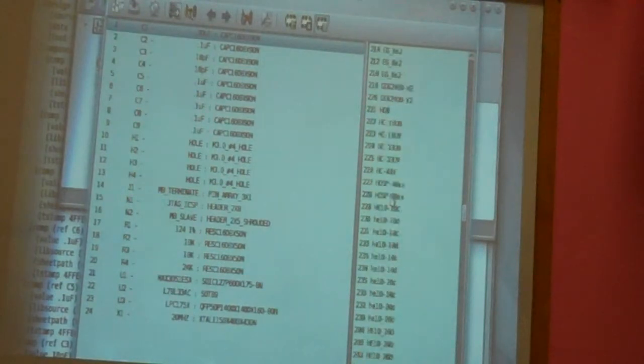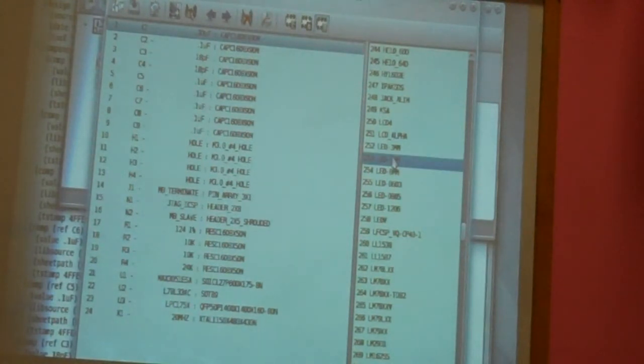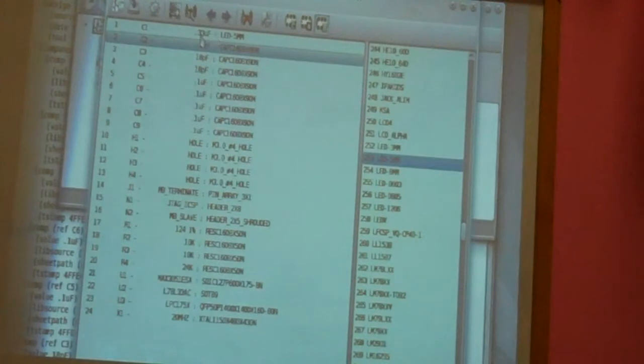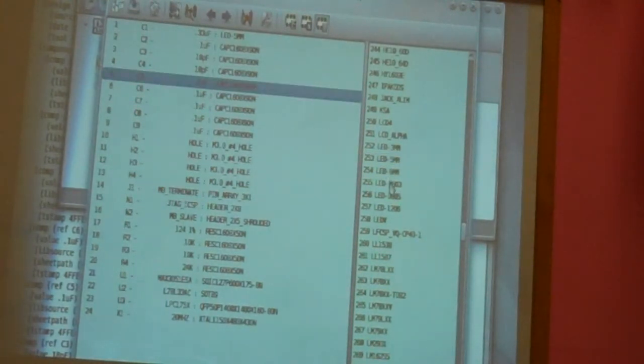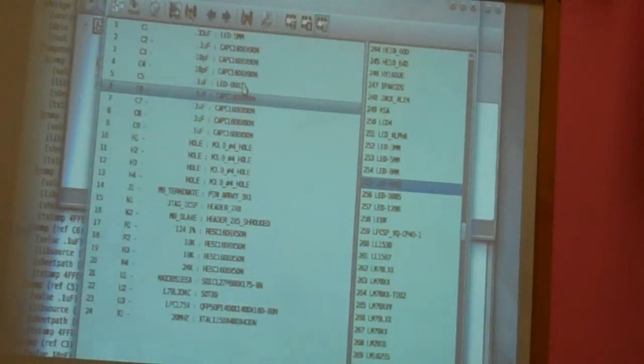and we're just going to pick one of these at random. I double clicked on it, and I just turned the capacitor from this footprint to an LED 5mm footprint. We can do all sorts of crazy things here. This one would actually work. That's an LED 0603. There will be checking that goes on later, but for now you can do any assignments that you want.